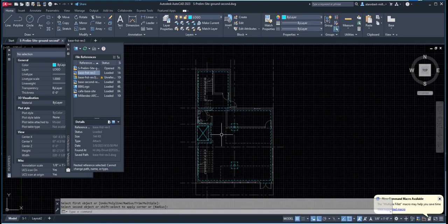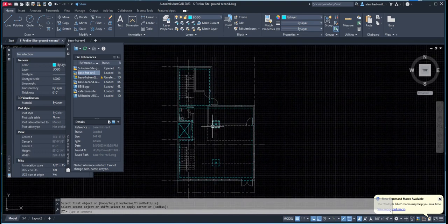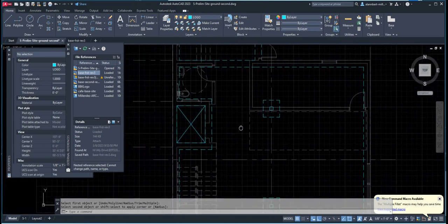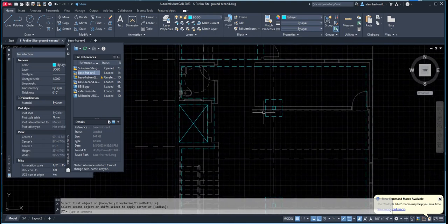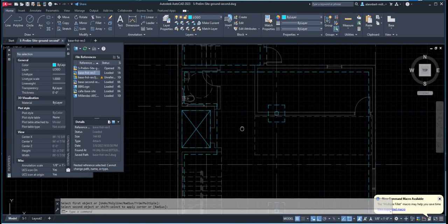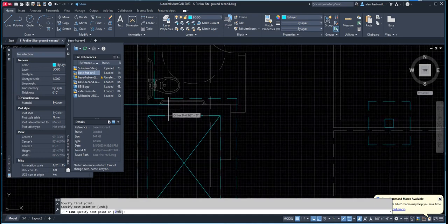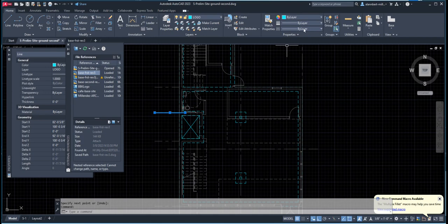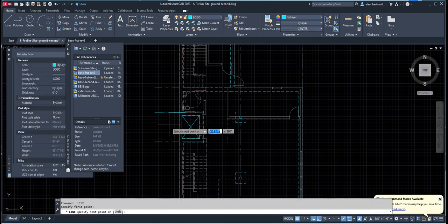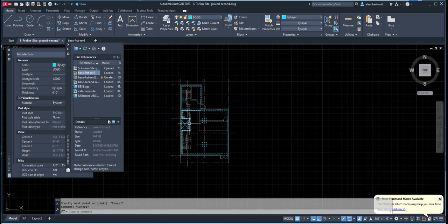So, the last piece is that any footing, any column should have its own grid. And if the architect did not put a grid on there, the engineers would come in now and put their own grid. Okay, so they would match that grid wherever the architect put it. Okay, so let's have two here. And that line type would be center. Okay, and so they would just copy that as part of what the architect wanted.